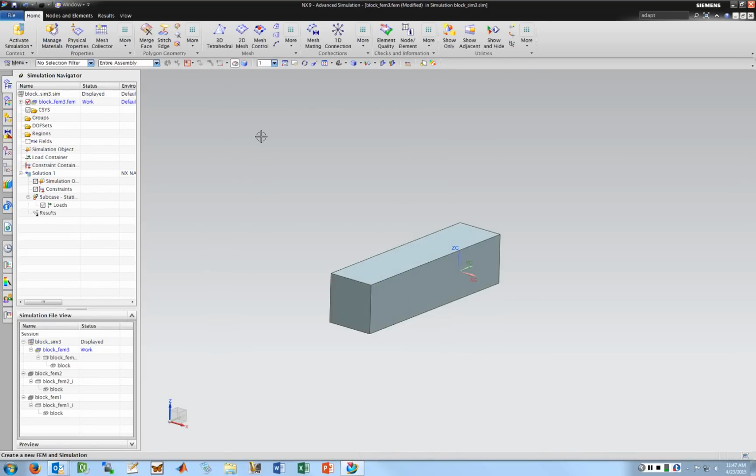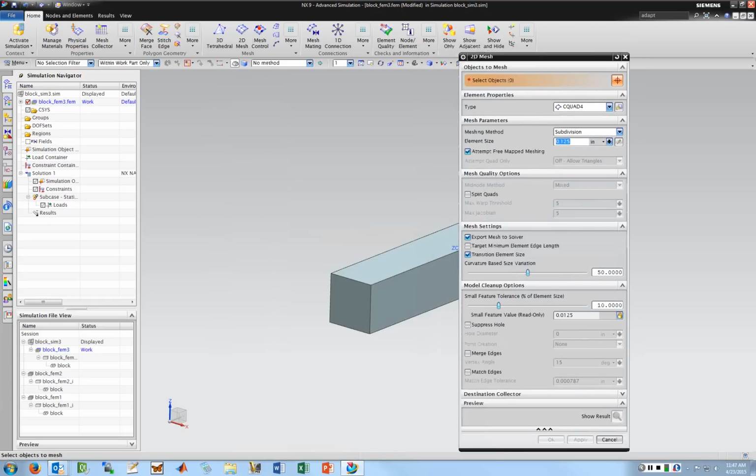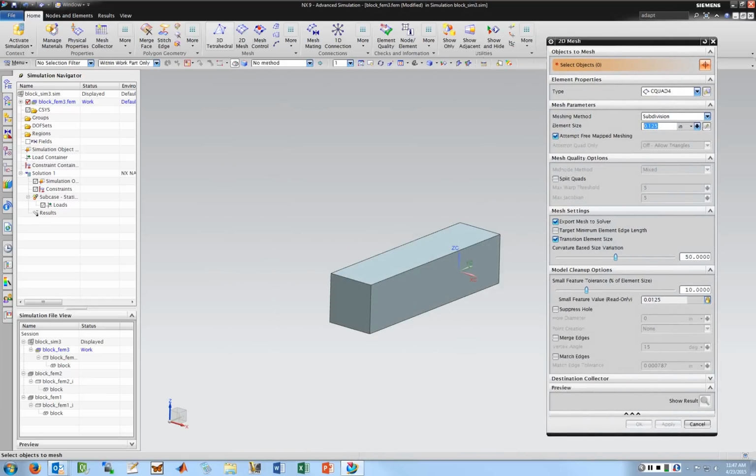I'm going to create a mesh. So I showed how to do a 3D tet mesh in previous FEA tutorials, so I'll get to that in a bit. I want to add mesh adaptivity to that. I want to show how to do a 2D mesh though. So for a part like this, if this was a solid part, I'd want to definitely do a 3D tet mesh or a swept mesh. I'll show how to do a swept mesh for this in the thermal part.